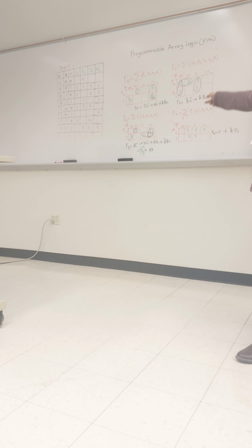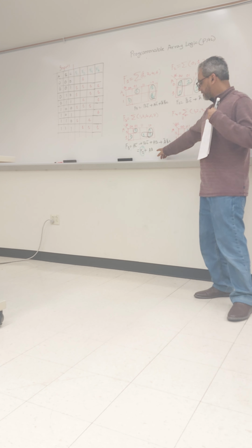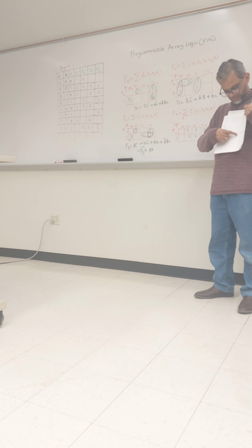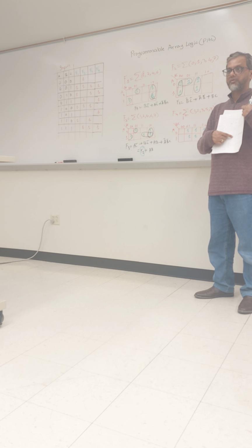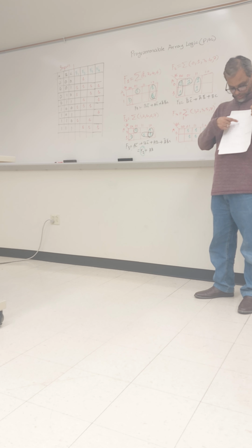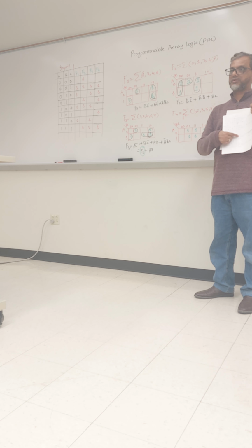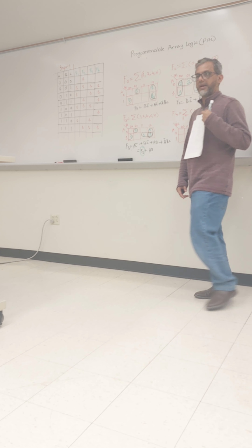So we have 4 functions, and we should have 4 OR gates: 1, 2, 3, 4. And here we will have 3 AND gates. Every OR gate has 3 AND gates, 3 minterms. But here we can see the function F3 requires 4 minterms. So we have to get a feedback here. Then we draw a line here, and we can give the connection to this one. Okay.